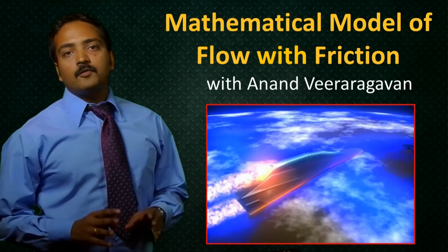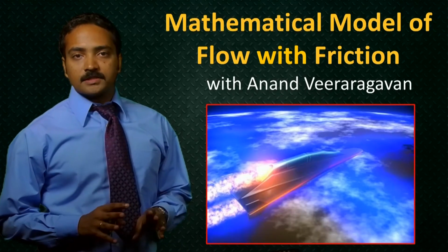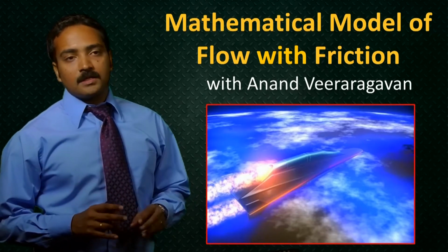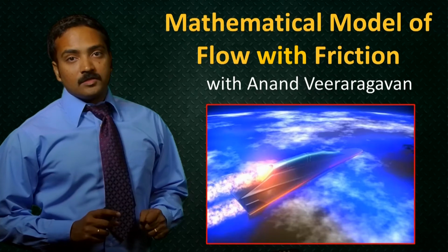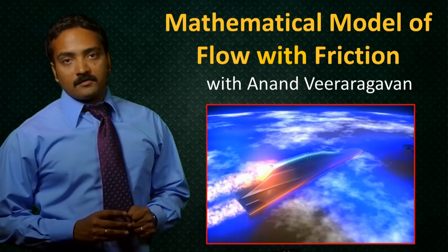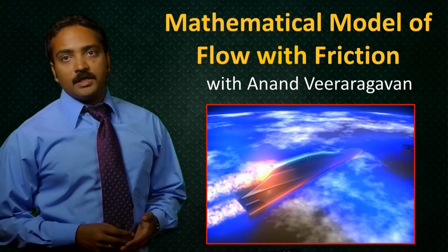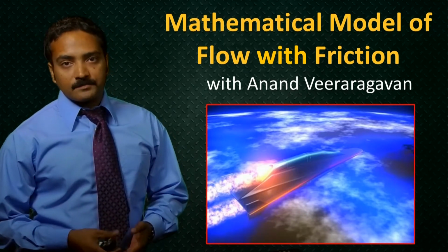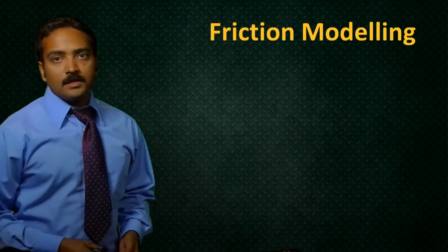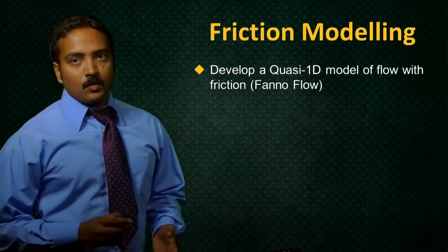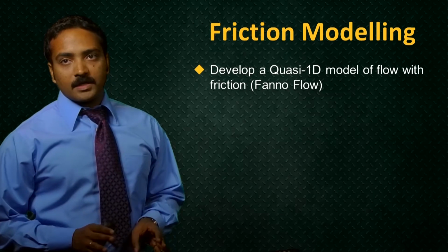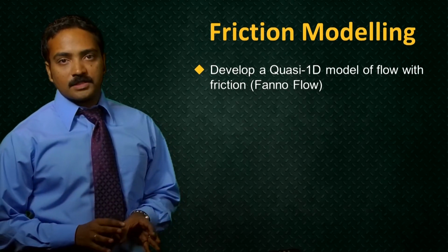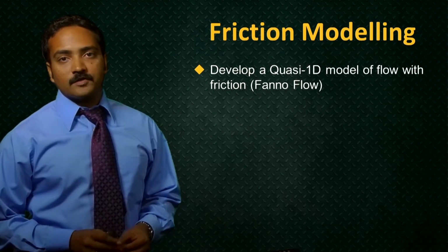So far, we've qualitatively understood what friction is and how it impacts a flow through a combustor. It's now time to make that a quantitative understanding, and to do that, we need to start off first by developing a mathematical model for flow with friction. So in friction modeling, what we will be doing is developing a quasi one-dimensional model for this flow with friction, which is also known as Fanno flow.